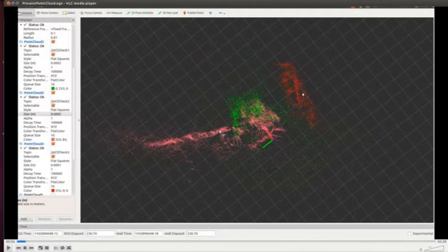And after the place recognition, when the central computer calculates the transformation between both robots, it transforms the red point cloud in the coordinate system of robot 2 into the coordinate system of robot 1, and the resulting point cloud of robot 2, represented in the global coordinate system, which is the coordinate system of robot 1, is the pink point cloud.